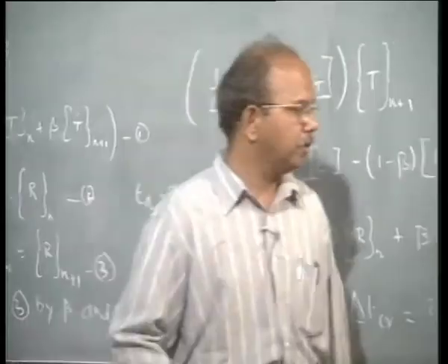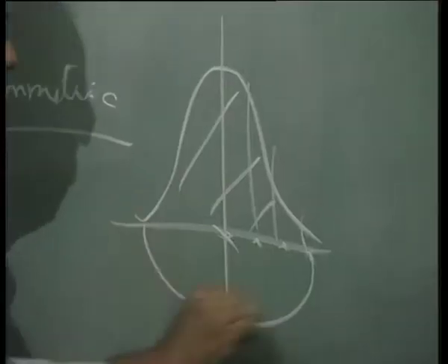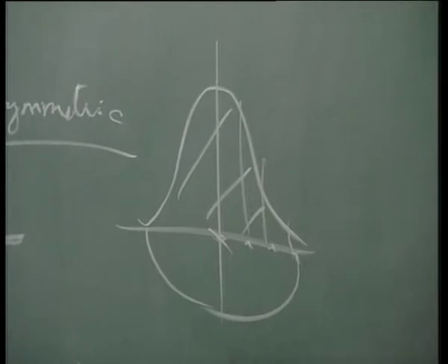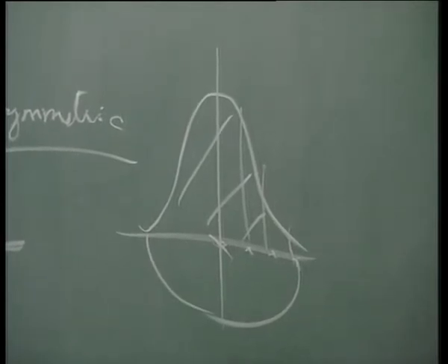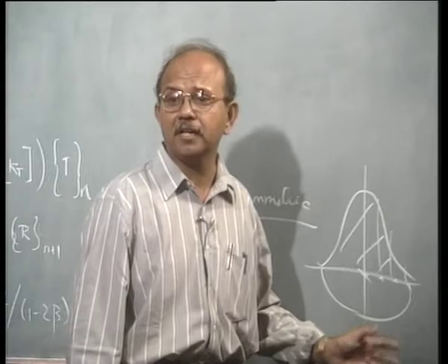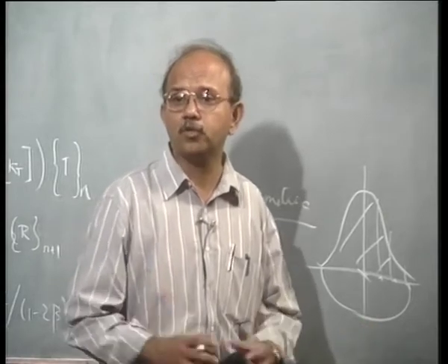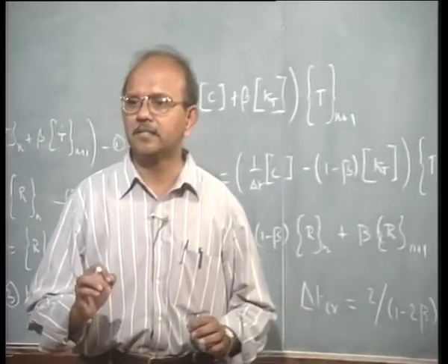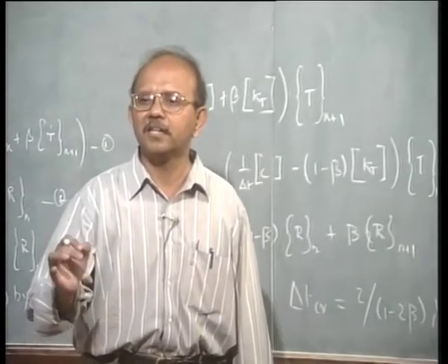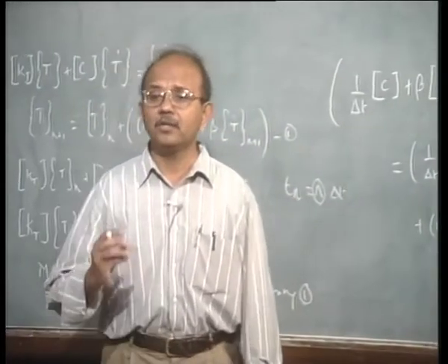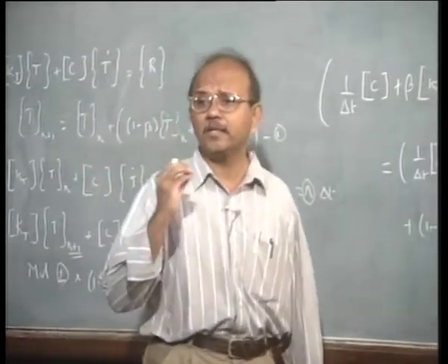There is going to be material melted below the surface, and we are not going to be concerned with convection effects that may take place in the weld pool and so on. We are considering this heat input, and of course we are also considering the latent heat as I had mentioned before.